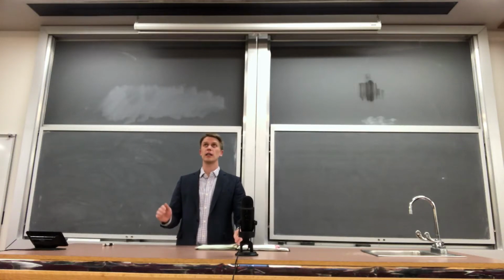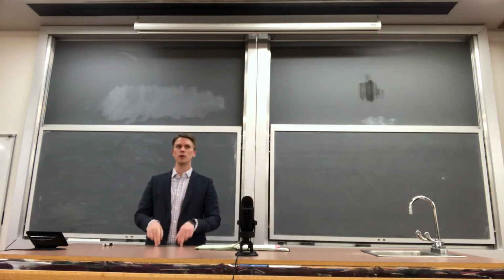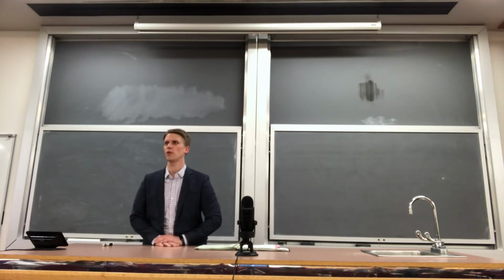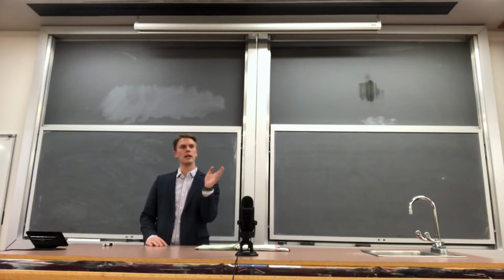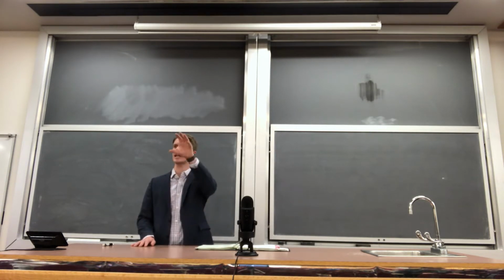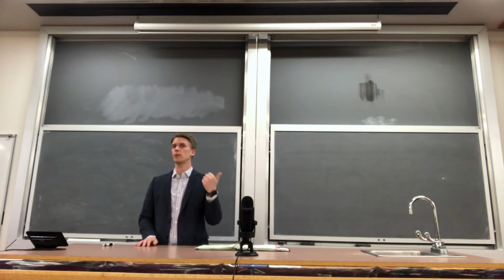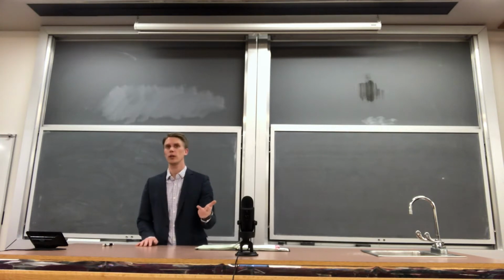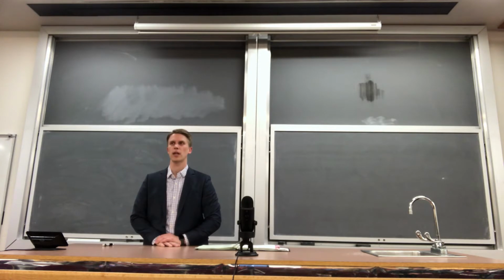So as of Wednesday, that wraps up our content on multi-component, multi-phase thermodynamics. We went through that pretty quick, in a couple of weeks or so, maybe 4 or 5 lectures worth of content, where we spanned all the way from humidity, which is one liquid phase evaporating into one gas phase, not a vapor phase, a gas phase, because then the gas can't very readily condense into the liquid. We talked about liquid-vapor equilibrium, solid-liquid equilibrium, gas-liquid equilibrium, liquid-liquid equilibrium. So these are basically interactions of all the different phases that we would possibly encounter for a separator.